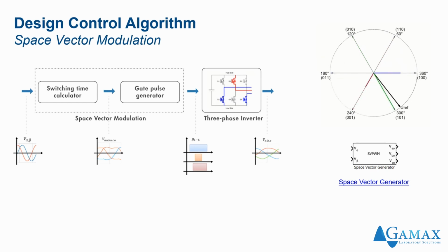So space vector modulation, also known as space vector pulse width modulation, we can implement these techniques, or we can also use pre-built libraries for motor control applications. By controlling the switching sequence of the three-phase inverter and the on-time duration of the pulses, any voltage vector with varying magnitude and direction can be described for every PWM period.